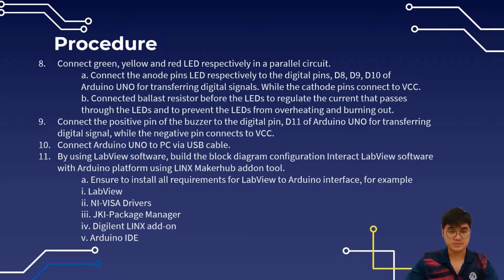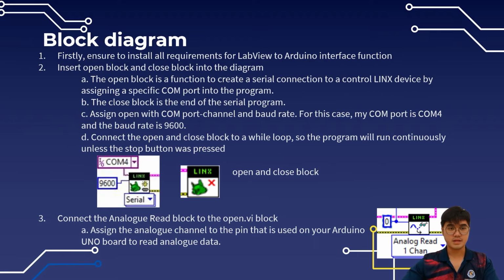By using the LabVIEW software, build the block diagram configurations to interact LabVIEW with the Arduino platform using the LINX, MakerHub tools. Ensure to install all the requirements for the LabVIEW Arduino interface, for example, LabVIEW, NI VISA drivers, JKI package manager, Digilent LINX add-ons, Arduino Uno, and Arduino IDE. Next, I will show you how we build the block diagrams.